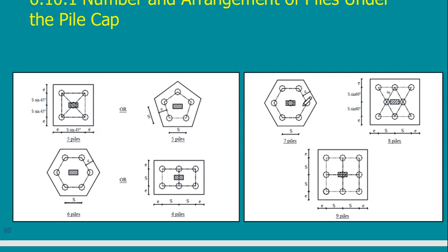So if I have here say 5 piles, and each pile can carry 200 ton, what is the maximum capacity? The maximum capacity can be 5 multiplied by 200, which is 1000. This is the maximum capacity. But can I guarantee it? No, I can't guarantee. What can happen? Maybe part of the friction will be lost between these piles here. The interface between the piles will lose some friction. So in this case, the total of these 5 piles may not be 1000